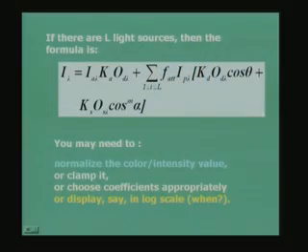because the dynamic range in the log scale will be reduced. That is what you use often for most signal processing amplifiers; they also use logarithmic scale for displaying. When the dynamic range of signals is very large, you use that in the case of displaying illumination effects. From a very small range, a fractional number like 0.001, to values up to 0.99, when you have values around 0.9 or more, values around 0.1 or even less will not be visible to the naked eye when you display them on the screen. So, display that in log scale. That is also another method by which the illumination dynamic range of pixel values is handled.